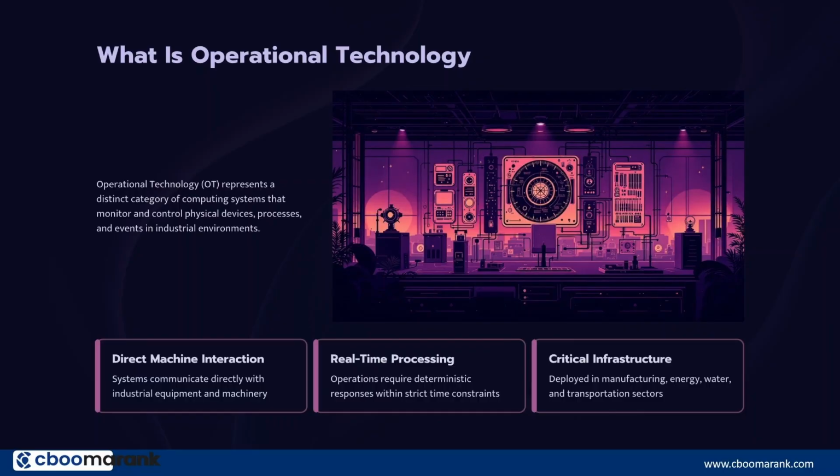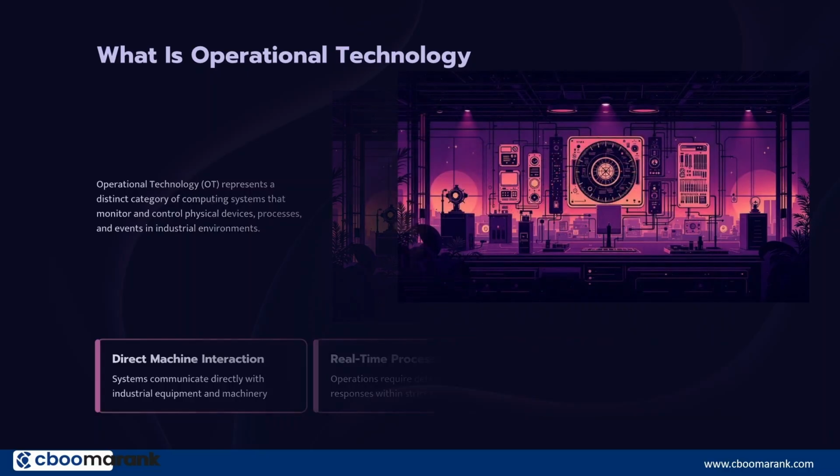This operational technology has its own key behavior since it has its own priorities. The first priority in operational technology is availability, then reliability, and then safety. Unlike IT operations, in IT they use the CIA triad: confidentiality, integrity, and availability. We will see it together. Let's take an example on this.